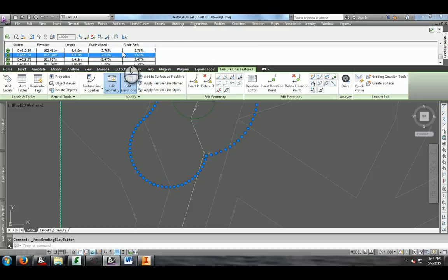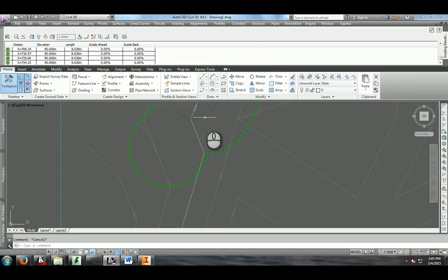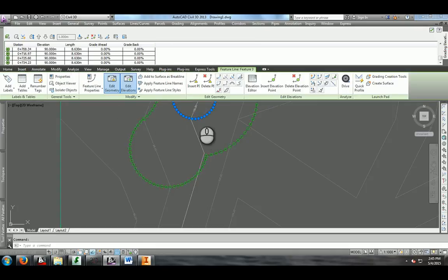So we're going to press Control A, which will select all of them. We want the elevation of all of them to be set to 90, and then I'm going to press Escape and select this. This is going to be set to 90, but I don't want it to be. I want it set to 80. Click OK. Nope. Select a cell, type 80, click OK.